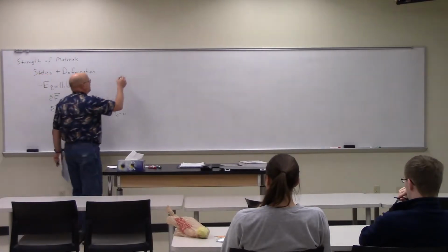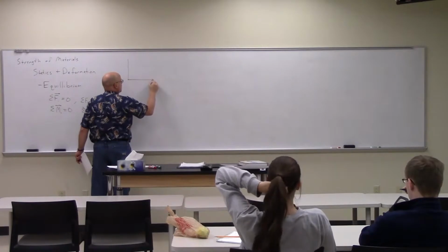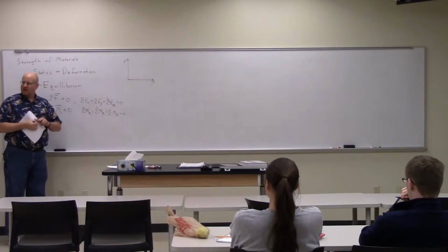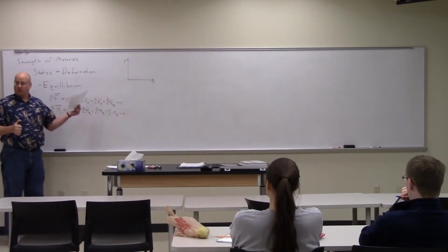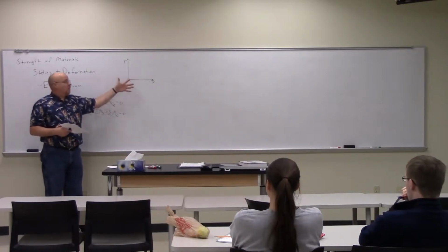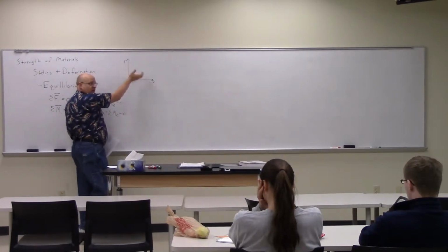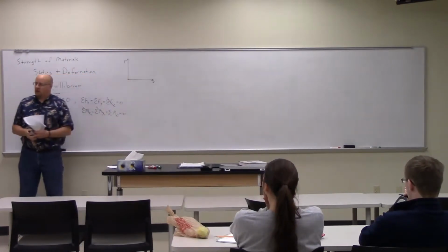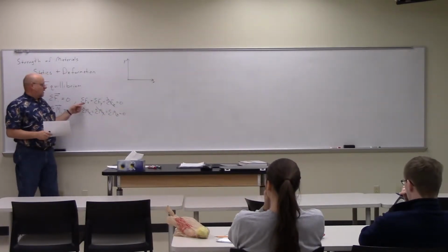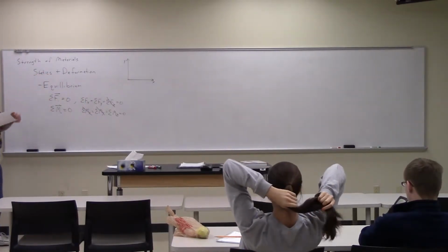Right? Because if my board is my 2 dimensions, then I can have forces in the x, forces in the y, but no forces in the z because it's a coplanar force system. Everything's in one plane. But I can have moments in the z. Right-hand rule. If I have any kind of a force acting out here, the rotation's always going to be about the z in a two-dimensional system. So the 3 pieces that exist in a two-dimensional system are the sum of forces in x, in y, and the moments about z. Everybody remembers that, right? So, okay.